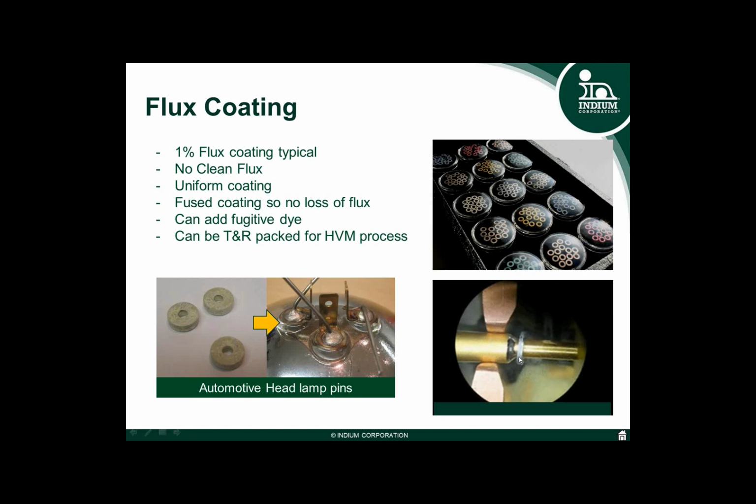The solder will reflow and capillary fill into those recesses, making that nice fillet you can see. So these are able to be controlled and packaged, as Bob said, in many different ways, so you can handle them as your manufacturing sequence allows.